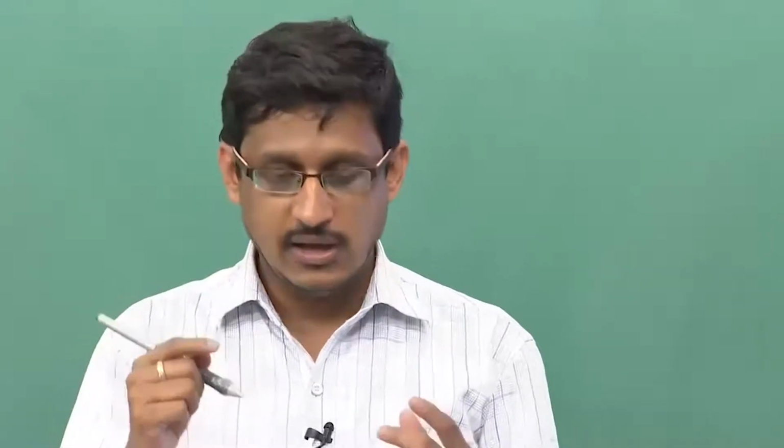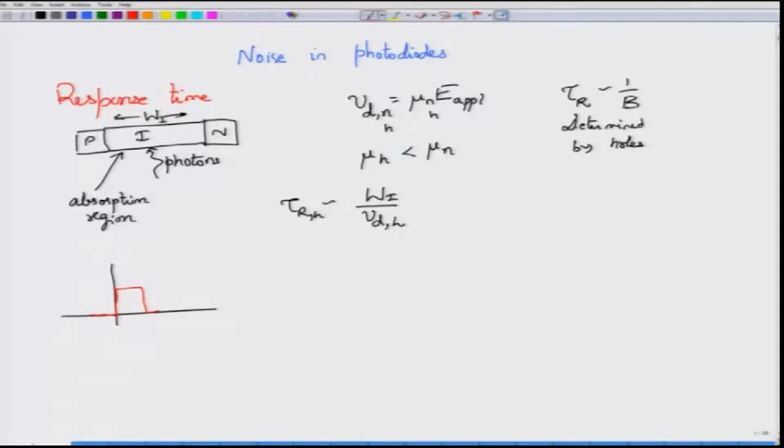These pulses have a very small rise time. If you give this optical pulse as input to the photodetector circuit and observe the current waveform generated as the result of this optical input, you will see that the current is not exactly following the shape of the optical input. Initially the current rises very quickly, and then there is a very slow process and then it drops off later on. So this initial region is the fast process that we have,